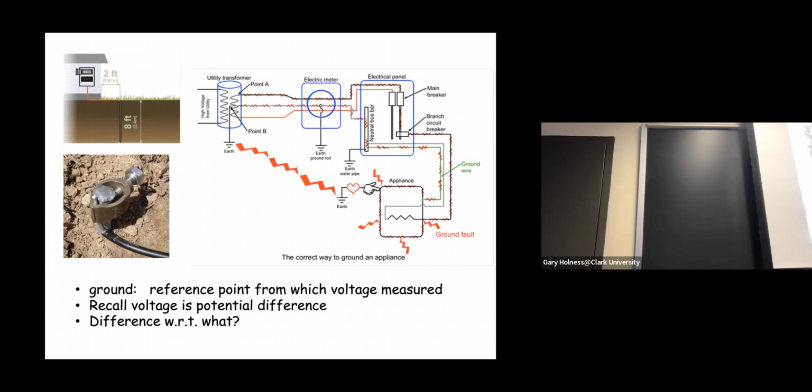And so this ground rod provides that same reference to ground, that stable state that's associated with the power utility, the electrical panel, so that when you plug in your appliances, that appliance has electricity going into it, but it's also connected to ground through your electrical panel, which has that grounding rod. Now, what that means is that should something happen, you touch your metal fridge, you're not going to get electrocuted because of this ground rod. And it was originally called ground because of driving rods into the earth, into ground. Any questions about this? No?